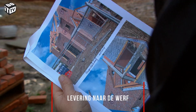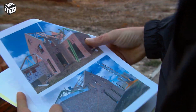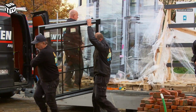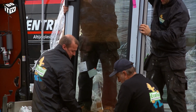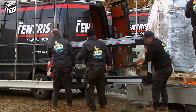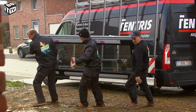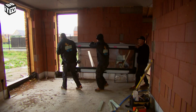Once the production is finished, it's time to bring the windows and doors to the site. A good planning ensures that for the ease of installation, all windows and doors are placed as close as possible. Especially with the large glass panels, this is indeed a job that requires a few skilled hands to handle effectively. Think about good ergonomics when lifting and carrying, ensuring the joinery cannot scratch. So provide something that the trim can lean against without getting scratched.